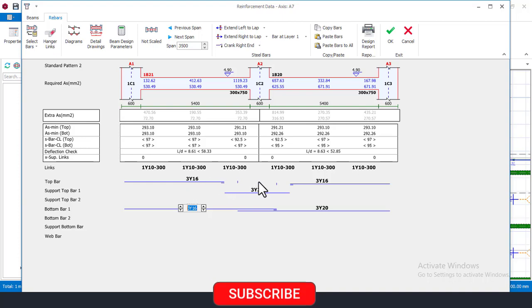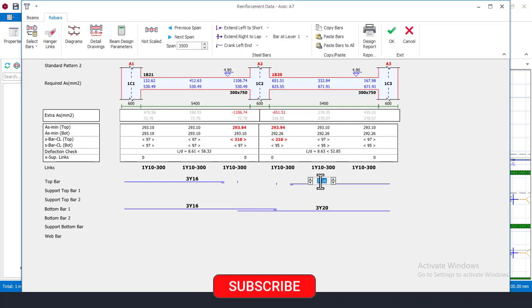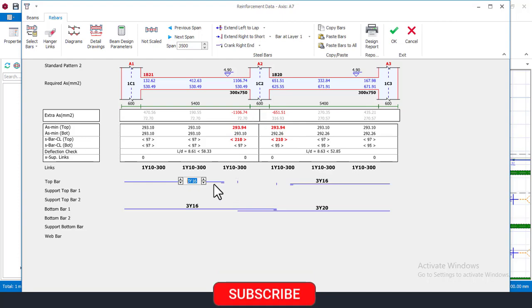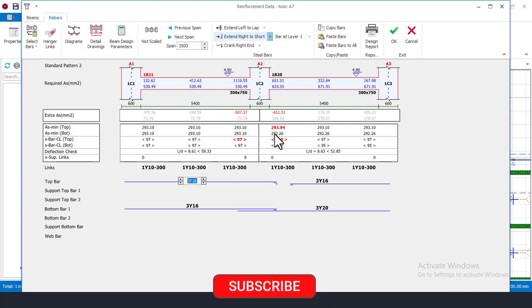So right now I'll have to reduce this first, reduce this entirely and remove it. Let me just take this off first entirely. Now I said there is not a failure, so I will have to extend my reinforcement into the column, or the support here and also into the support here. So right now I will have to come here, click on this first, right click here and extend this into the column. So I'll come here right now, click on this and then say extend right to lap. Okay, and also come here again right now and extend left to lap. Okay, so always use lap.